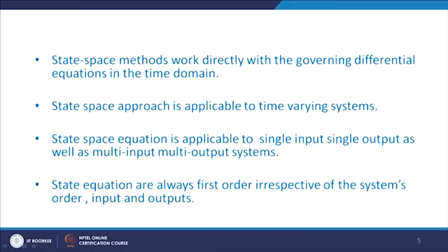Third, state space equation is applicable to single input, single output, as well as multi input, multi output systems. In practice, most of the systems are multi input, multi output. Therefore, we should have techniques of stability as well as control design which are applicable for multi input, multi output systems. So, that type of approaches, particularly stability and control design, are easily available in a state space approach, whereas it is very cumbersome in case of the classical approach.